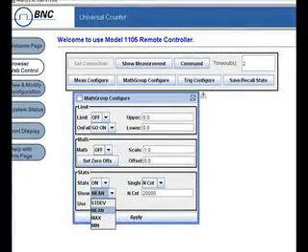Input config allows you to toggle input impedance between 1 megohm and 50 ohm. Toggle input coupling between AC and DC. Toggle attenuation times 1 and times 10. Toggle filter between none and 100K. Select front or rear inputs. User can do measurements from the rear terminal by pressing the soft key under Input. An option is required for rear panel connectors.